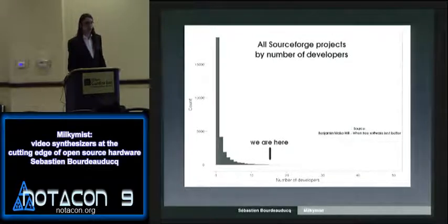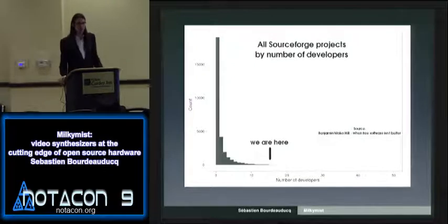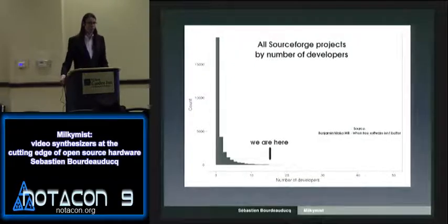Yeah, I am. It's DDR1, by the way. Well, right now, but we are going to switch to DDR3 probably in one year or something. DDR3 is pretty hard because you have a very high clock rate. You have a lot of serialization between the DRAM core and the I/O frequency, and the current architecture cannot really deal with that very well.